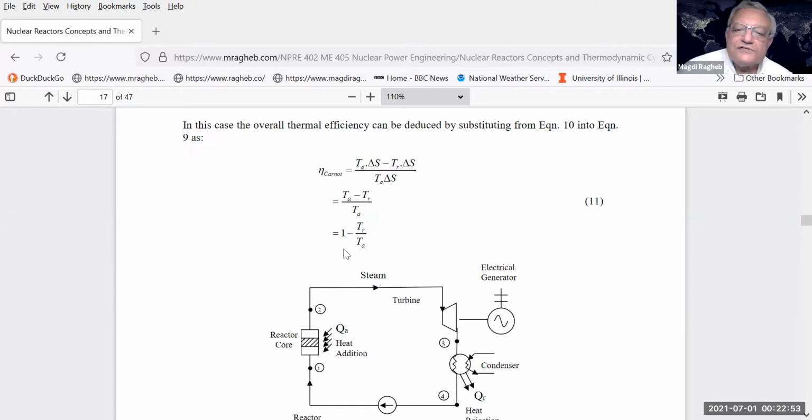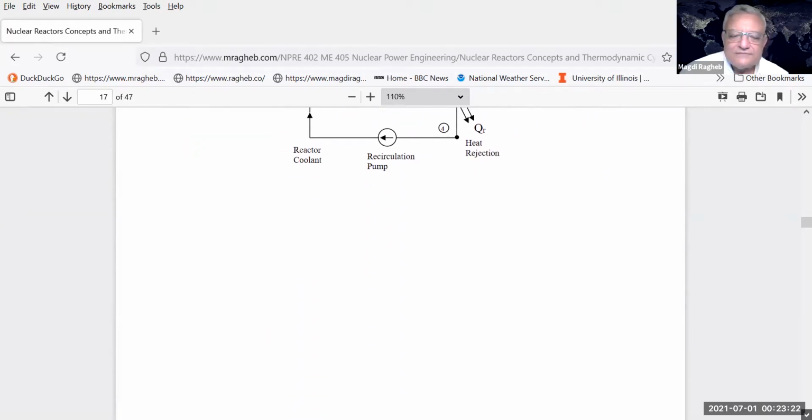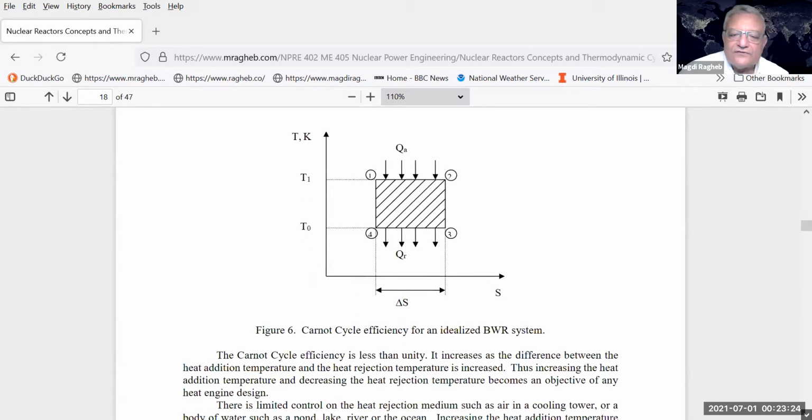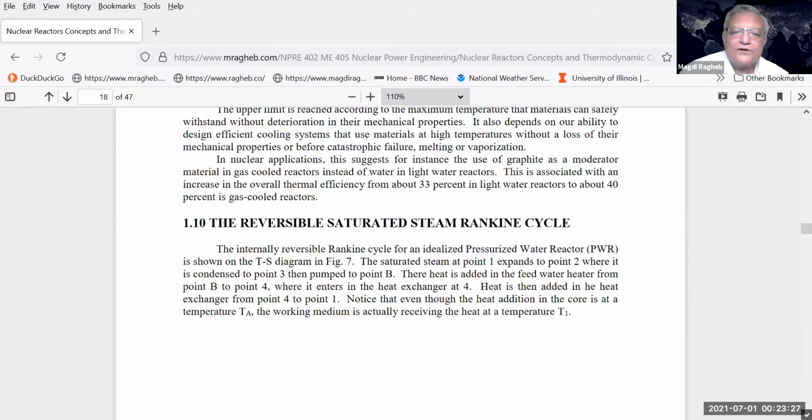Notice that the efficiency must be less than 1. And notice, please, also that when you apply the efficiency equation, I repeated, because many students still in tests or exams, or hopefully not in the workplace, mistake that T here as being the Celsius temperature. It is not the Celsius temperature. This is a thermodynamics law, and T here is in Kelvins, 273 plus degrees Celsius. All right, so that represents the boiling water reactor.